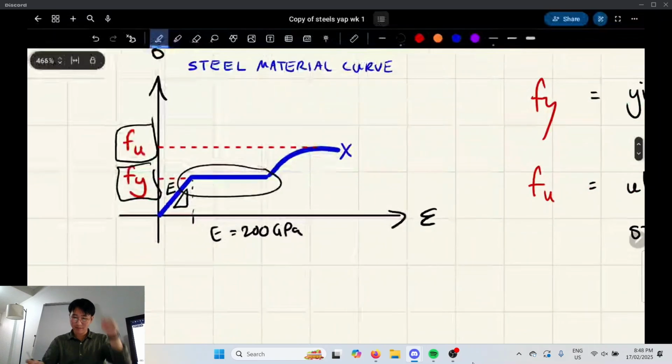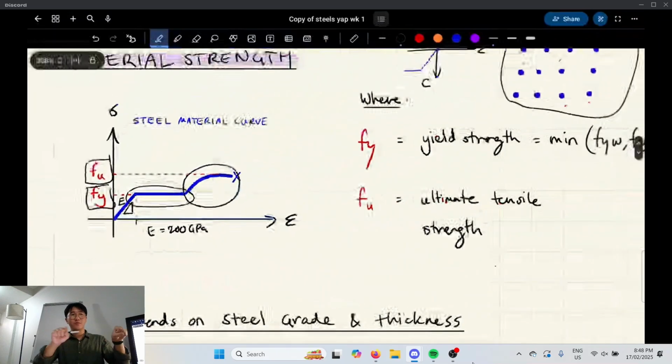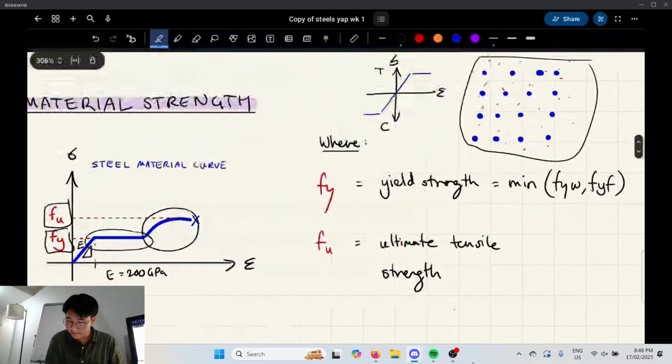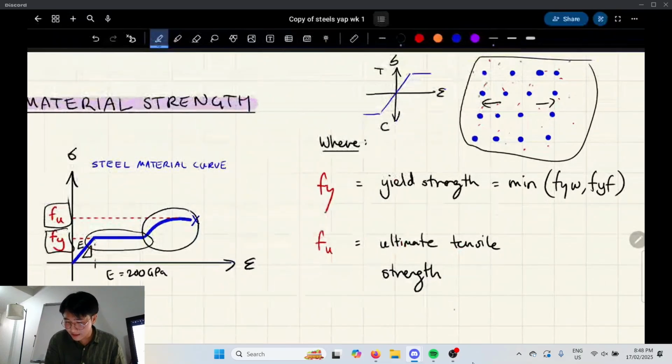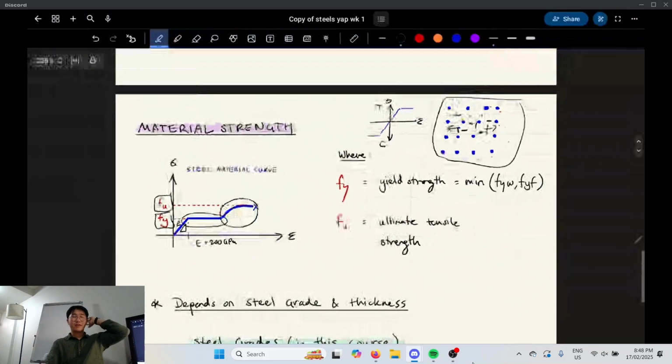And then at a certain point, it's going to do strain hardening, which is where it gains a little bit more strength because of the dislocations from the yielding. So you're pulling this apart, the dislocations start impeding on each other, and it actually gives itself more resistance than even its yield strength. Does that make sense? This is something that happens in tension. Yeah. Okay.